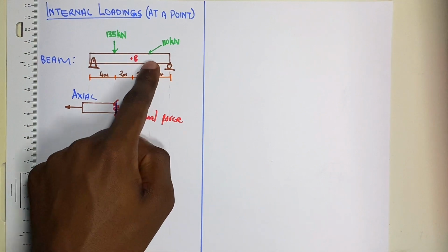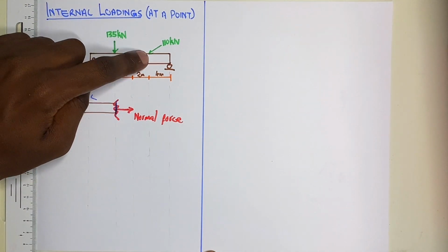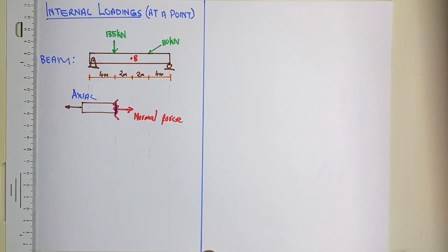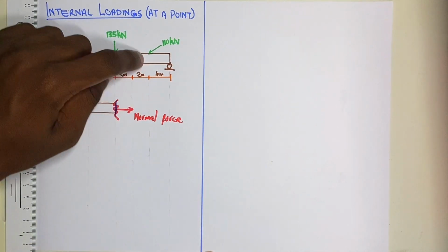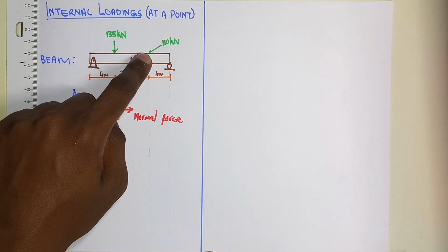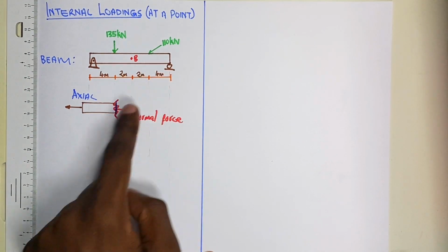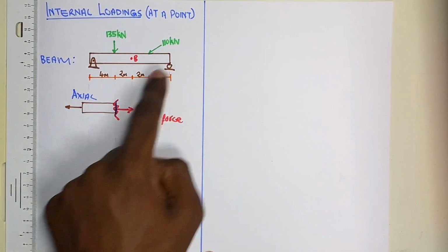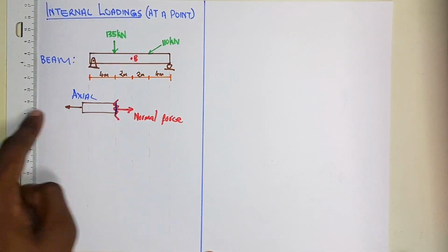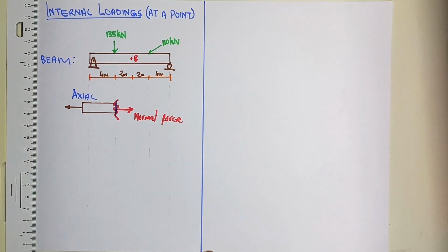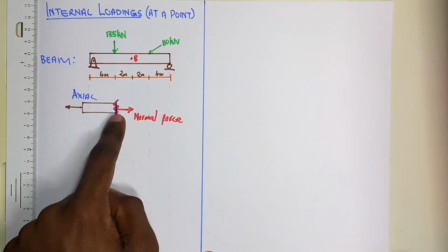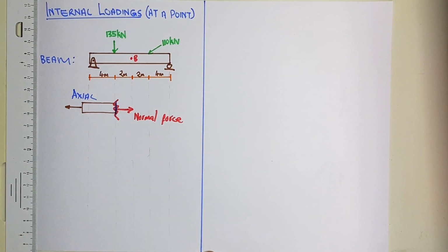Even if we were looking at the effect of a force like this one of 110 kilonewtons, but at an angle, it would have a component that is acting axially. It would have an x component, a horizontal component, that would be pushing in the x coordinate direction. Therefore, we would have an internal normal force that is acting on our member. We'll look at more examples to see how it will react to different types of forces.